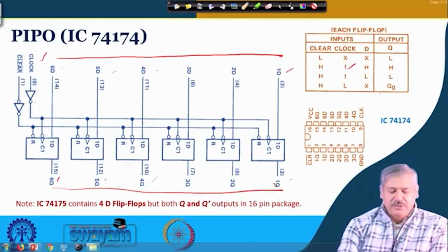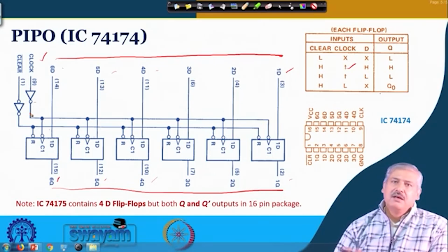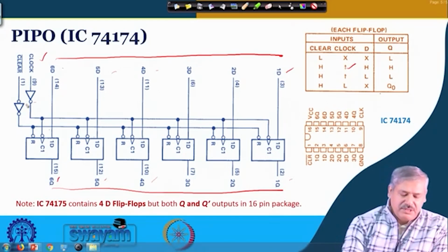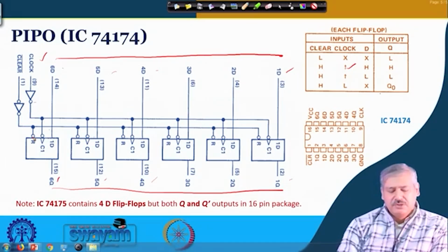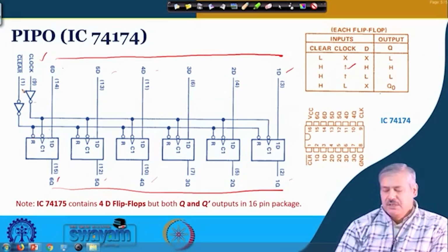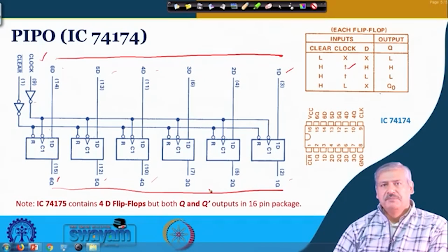And if you are looking for resetting or clearing it, you can do all the flip-flops together. So, it is a common clear. There are 2 bubbles here and then a bubble, so basically it is active low. If you put a 0, irrespective of the other values, it will become reset. Is it okay?